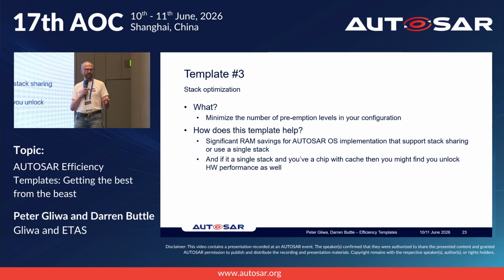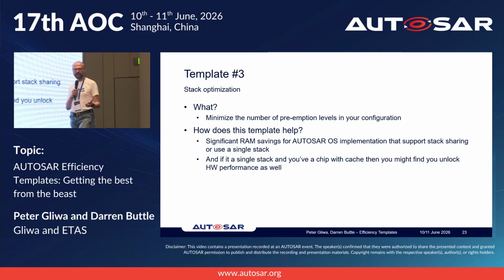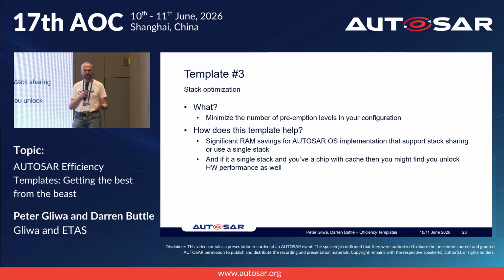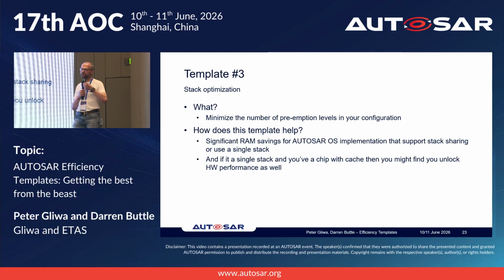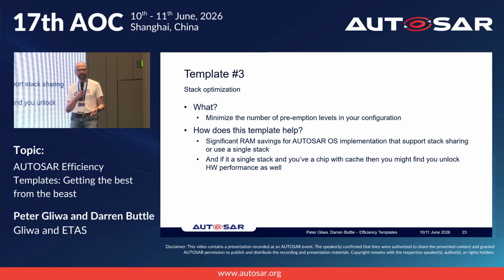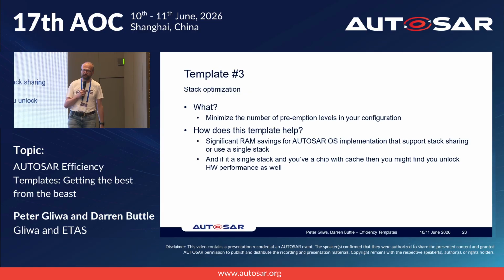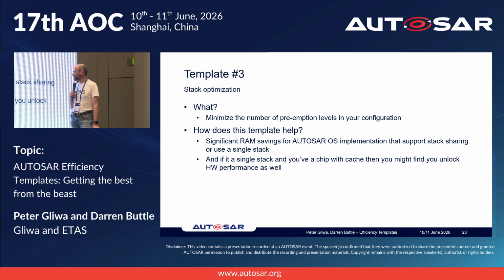stack. So there are basically 3 ways of building the AutoSAR stack management. You either have a stack per task, and then you need to allocate space for each of those stacks, or you might be able to have things where tasks share priorities or share an internal resource, basically put those on the same stack, and then it's the maximum of that. Or you can apply that design model across the entire OS as well and just have a single stack for the entire operating system. If you want to do that, you need to come and license the patent for that from us, because we've got some patented stuff that makes extended tasks work with them.